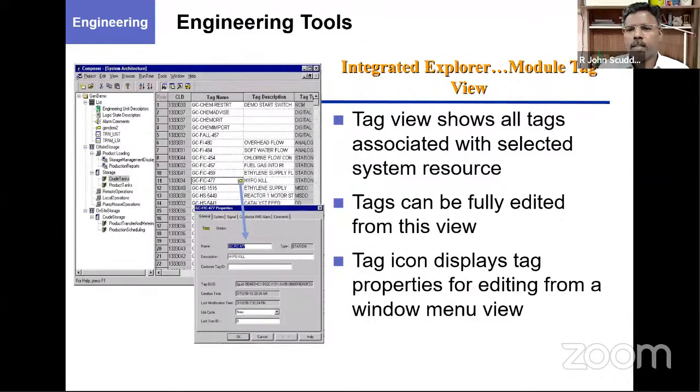As I told you earlier, for every parameter you can generate an alarm. For every parameter you can generate a color change. Imagine the normal operating pressure of a power plant is 0 to 145. Beyond 145, if you want the color to become red, so that operation engineers will get alerted, those things are possible. You can change colors. As soon as it becomes more than 145, you can generate an alarm. And in some places where it is very dangerous, you can give a human voice alarm. Some recorded human messages can come out, like in your railway stations, where you have recorded voice messages. So many things are possible with DCS.